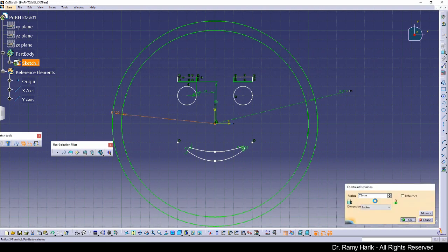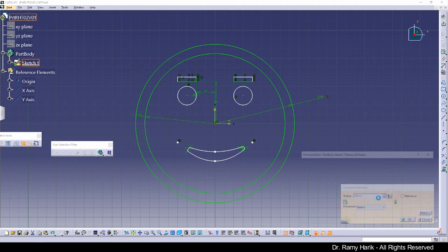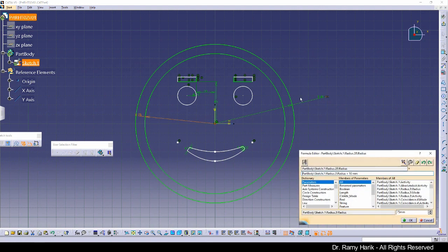And this is the power of the way that we will be learning about design: to make sure that we do things in a certain way that is parametric. So at this stage, we have created the formula. I am going to demonstrate it. What we did in here is once again select edit formula, then select the other dimension and add the operation the way that we want. You can do times 2, you can do plus 10, and so on.